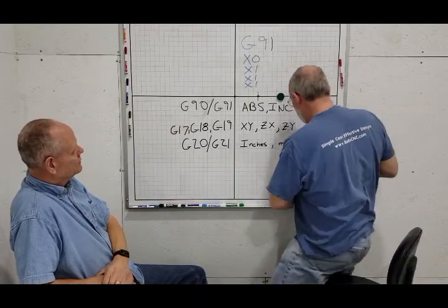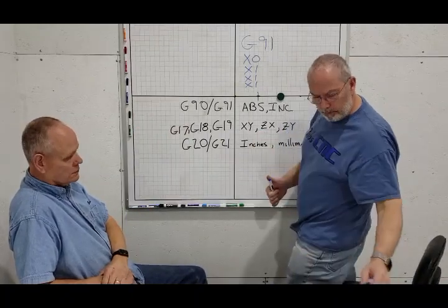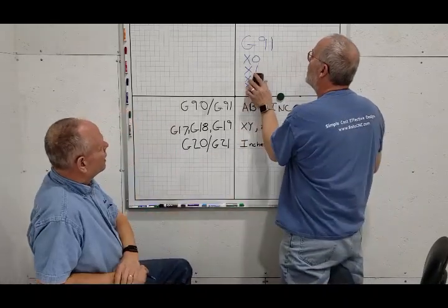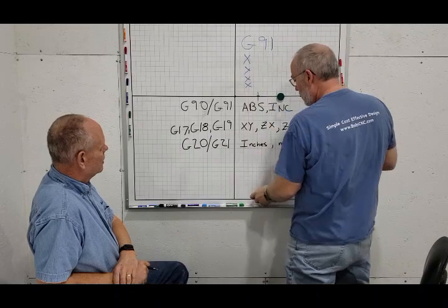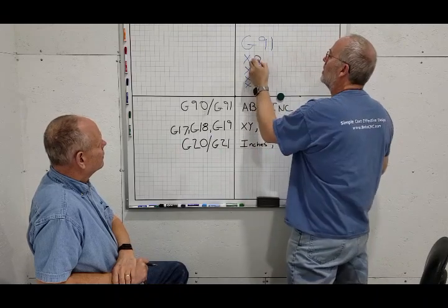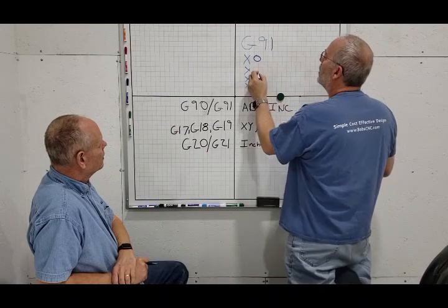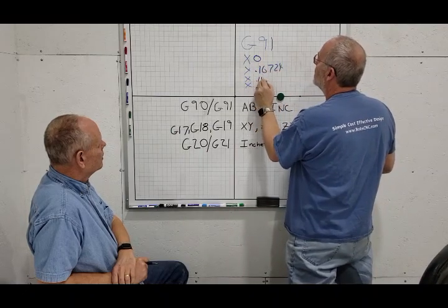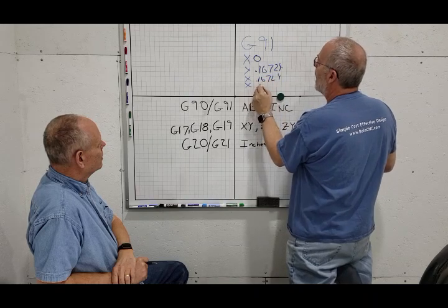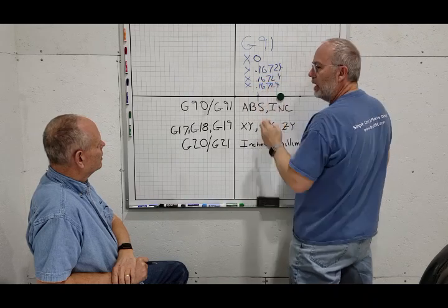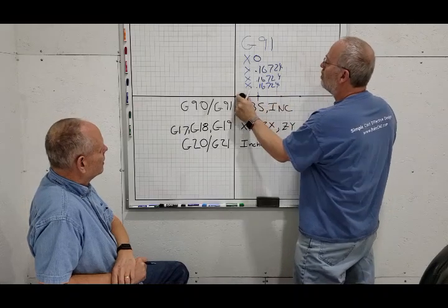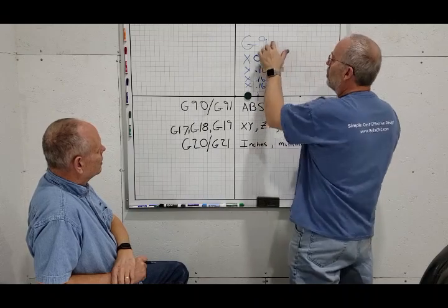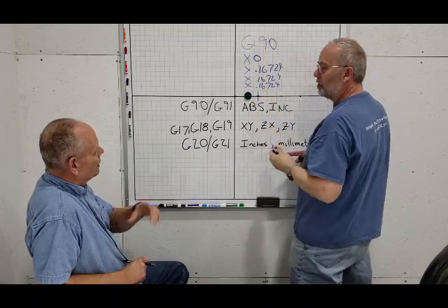Yeah, so let's just do that so that we can see it. Where is our ratio? There it is. Here you go. So let's just say that we started, our first one, we started at 0 because we're conscientious of making sure that we're at the right spot. So we want to go 0.6724, right? 0.6724. We could just keep typing this in, right? And we would go over 0.6724, another we would add and add. If we, of course, were in the G90 mode, it wouldn't be doing anything. It would just go to that one spot.